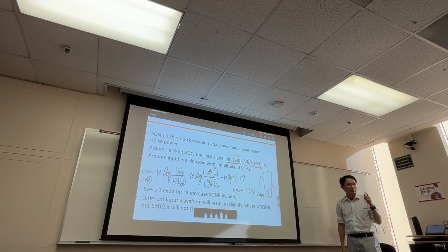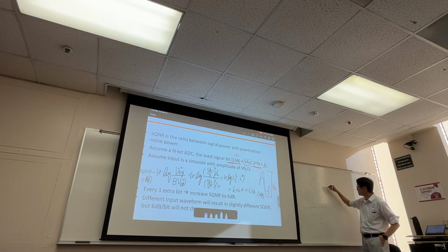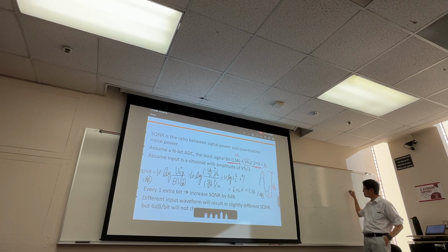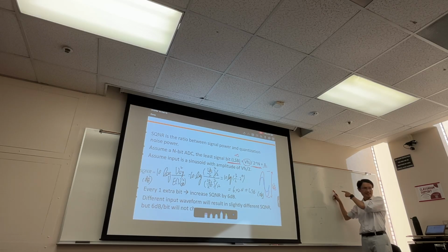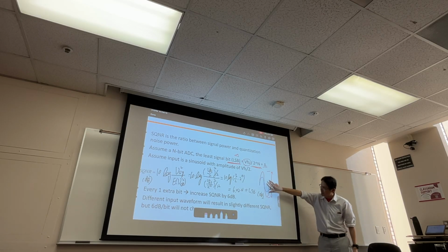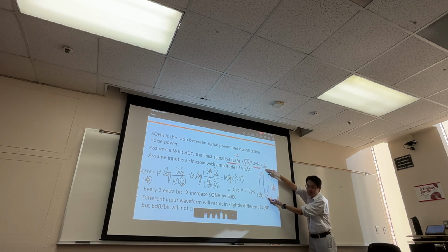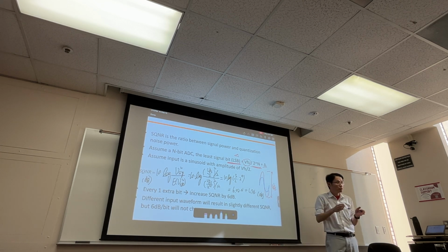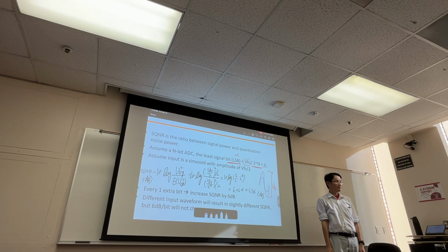Remember in the first lecture I showed you in a wireless system, right? So usually they have the amplifier, right? And then they have something and they have ADC. So now you know why. Why do I need an amplifier before the ADC? Thank you, because I want this to expand as close to the full swing as possible.